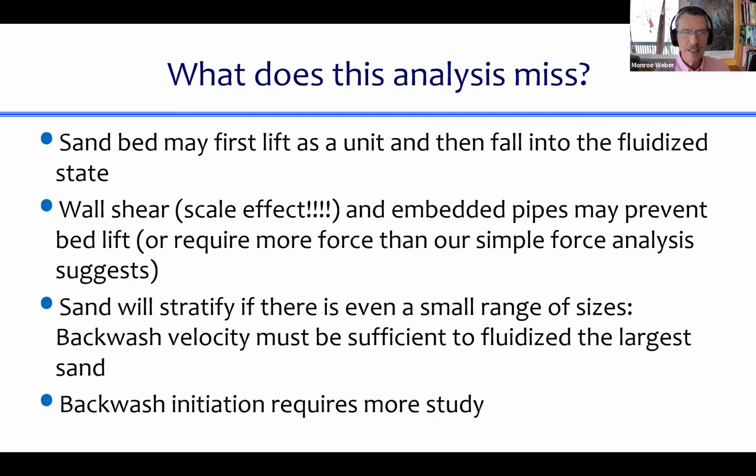And this transition, I feel like is worth some more research, because some funny things must happen, especially once you think about the fact that ultimately there's dirt in the filter. And so there's actually head loss as water is trying to flow through the pores of the filter as you're trying to fluidize it. And my best guess is that when you start pushing water quickly up through sand, at the very first instant in time, what happens is the entire bed lifts a tiny bit.